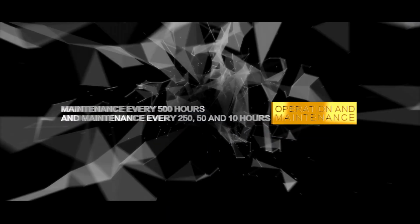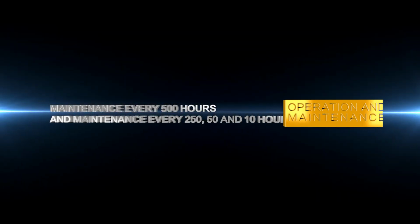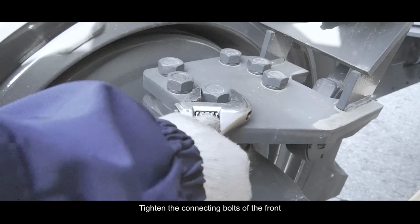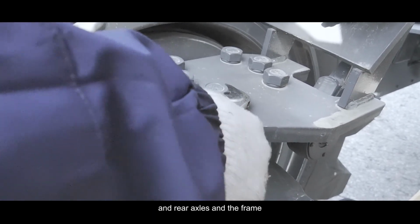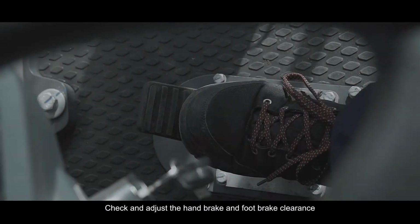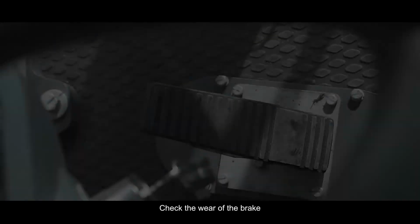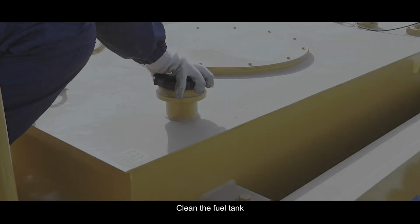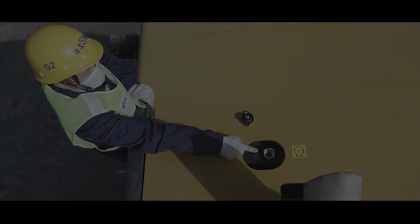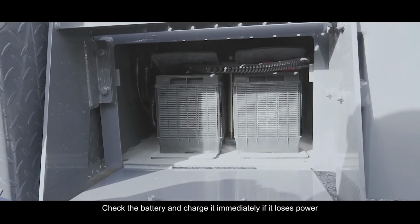Maintenance every 500 hours, together with maintenance every 250, 50, and 10 hours. Tighten the connecting bolts at the front and rear axles and the frame. Check and adjust the handbrake and foot brake clearance. Change the diesel engine oil. Check the wear of the brake. Clean the fuel tank. Clean the dirt of the water cooling system. Check the battery and charge it immediately if it loses power.